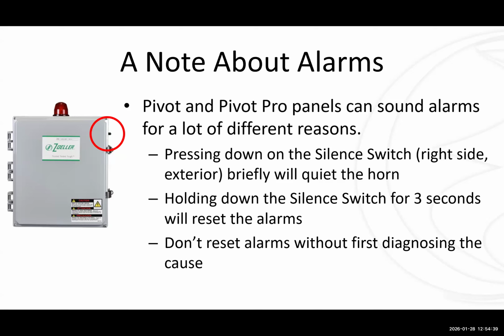So it's fine to silence it. Just tap that switch and silence it, but don't hold that switch down or you'll erase the history of what's going on there. Now, if you have this connected to ZControl, if it's connected to the cloud, whatever alarms have happened will already be stored in the cloud. Even if you reset the panel, it'll be stored in the cloud. But still, it's just a good idea: if you go to a panel and it's alarming, don't reset the panel before first studying the alarm.